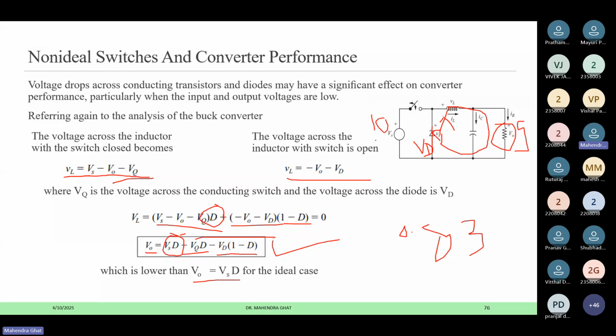Try to just take one example: you will have power supplies, DC power supply, so there you can get any voltage. Say I will have a 10 volt input power supply, and I want to get 5 volts. So you can get the source. Then from that you design the inductor, then design the capacitor, then you can consider the switch, diode, and all that kind of thing. And to switch this switch on, you will require the PWM.